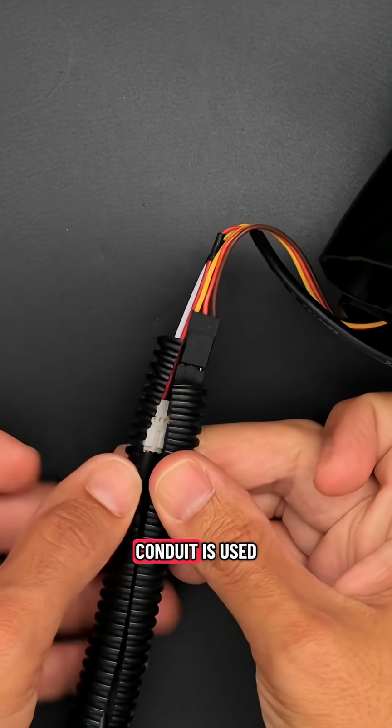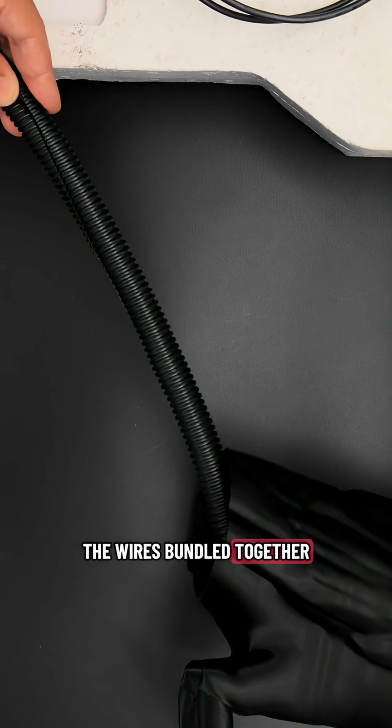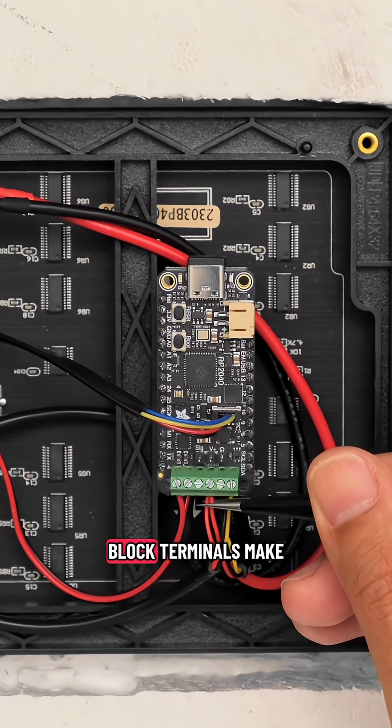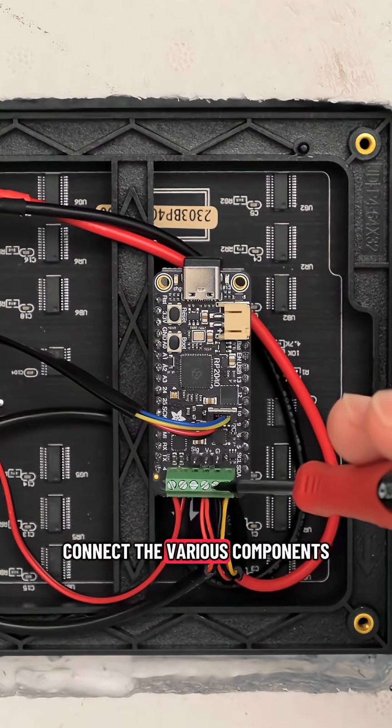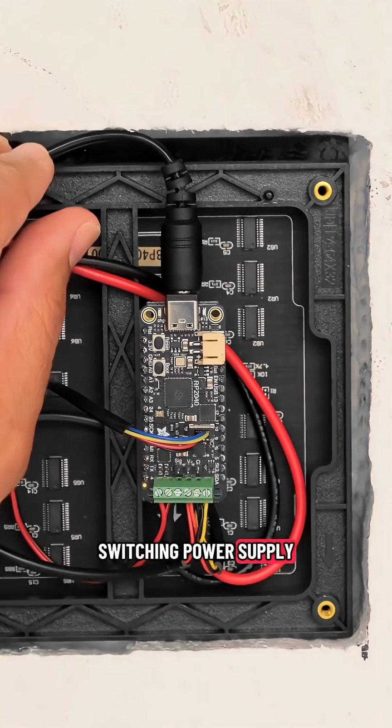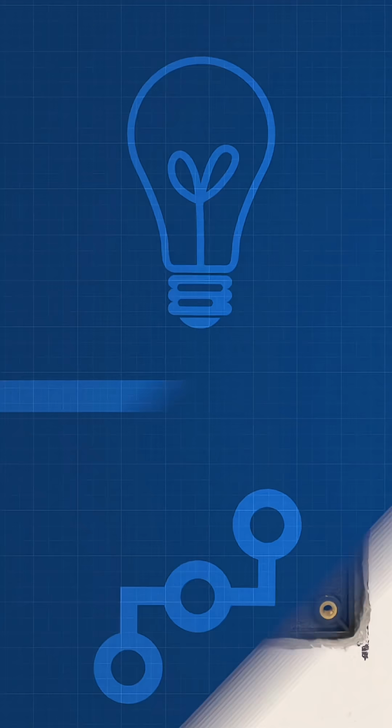Pieces of black conduit are used to help keep the wires bundled together and hidden. The Feather's onboard STEMMA QT port and screw block terminals make it easy to connect the various components. Everything gets powered by a 5V 4A switching power supply so it can haunt all night.